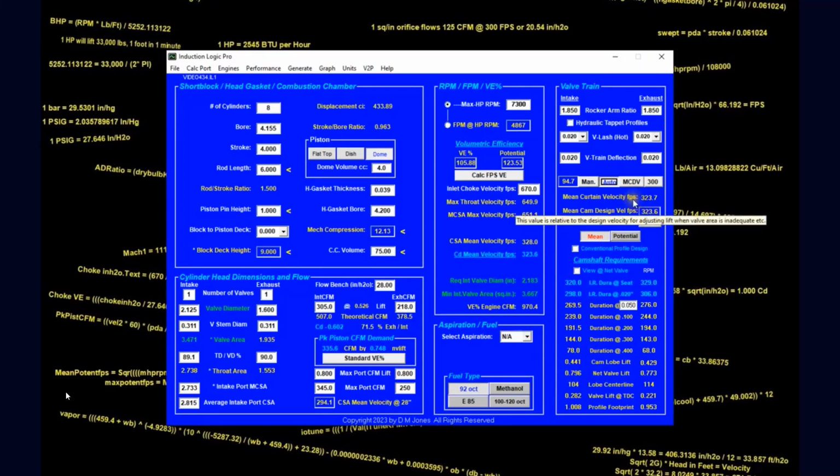The farther you exceed your valve area, the more lift will be added to compensate. So, you have now learned why at higher RPMs, the engine requires an unproportional amount of additional valve lift. It is to compensate for the intake valve diameter not meeting the minimum required valve diameter. Now, back to 7,400 RPM and the peak piston CFM demand. The port can now supply the demand, as raising the valve lift puts our 340 CFM at 768 thousandths valve lift.